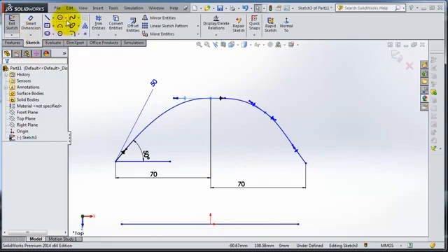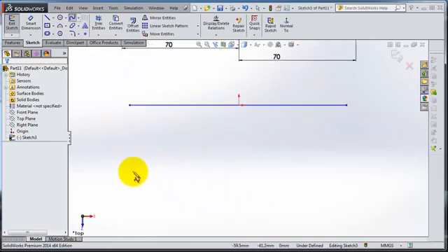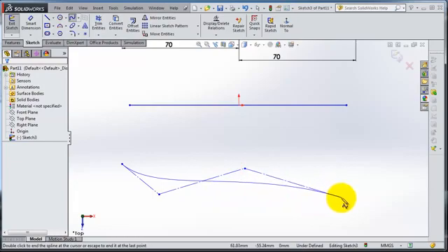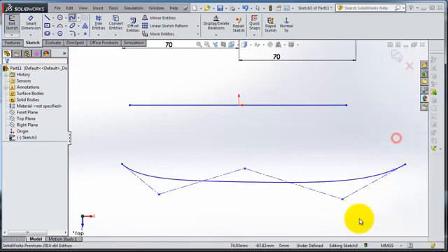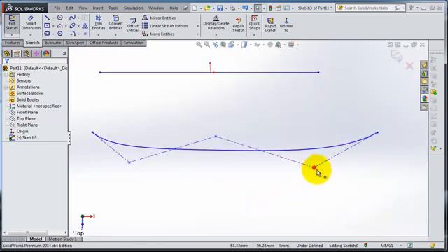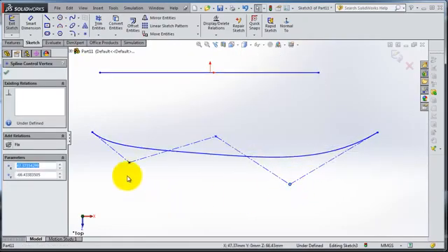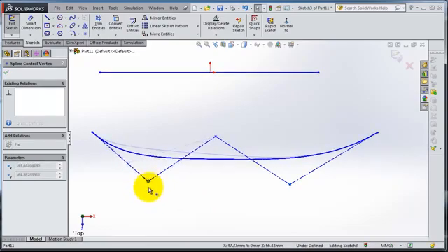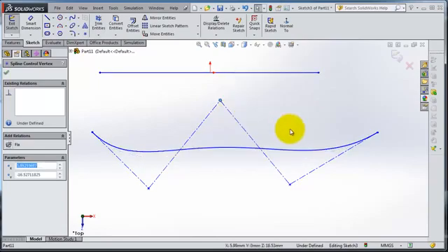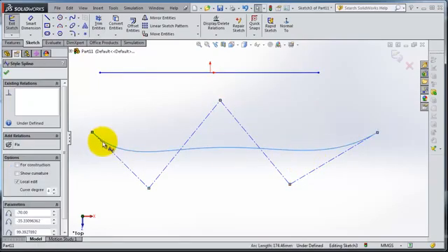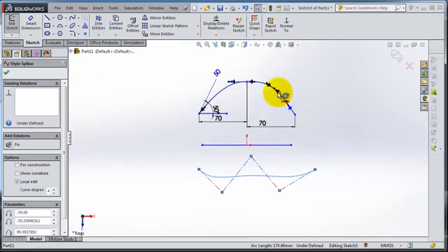And now you have a second type of spline, with guiding lines as a way for more control of your spline. You'll notice your spline is contained inside these guiding edges or lines. If you select that point, from that point you are able to control your spline. As you notice, you don't have the handle and the size as shown in the previous type of spline.